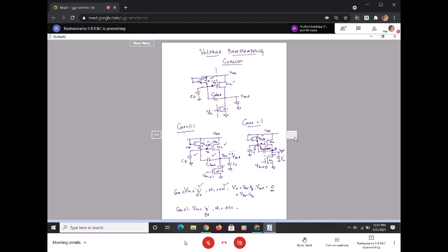You can see that voltage across capacitance cannot change instantaneously. So now this I C boot and the same current is flowing through the CS. I call it ICS, I C boot and ICS. So what is the current flowing through C boot and CS now? Are they same or are they different? Because there is no path here.